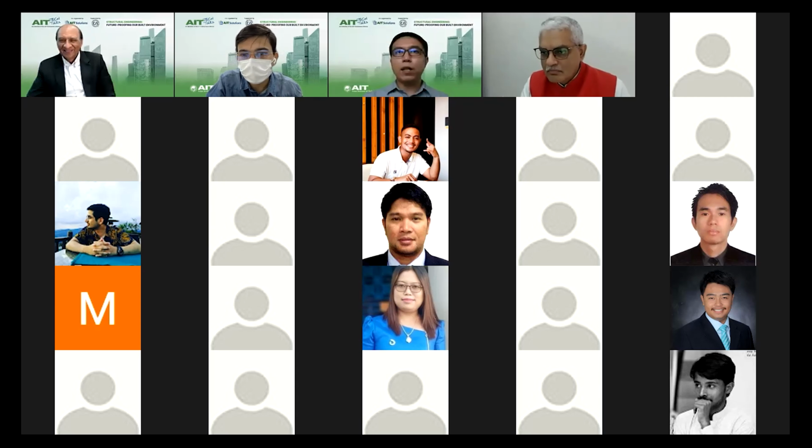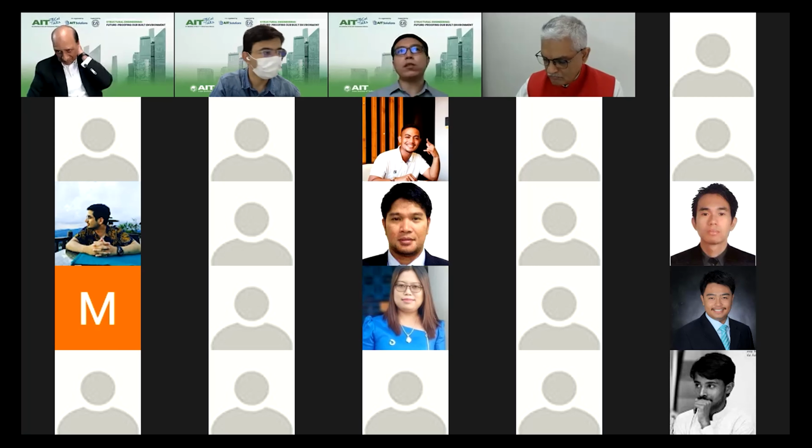The next question is, is there a limitation of PBD to use for certain importance level buildings? Yes, we can. There is no limitation in PBD. Actually, for important buildings, we had better use PBD. In the PBD guidelines for tall buildings, they also have the importance factor. For an important building, we have to multiply our responses by those importance factors.